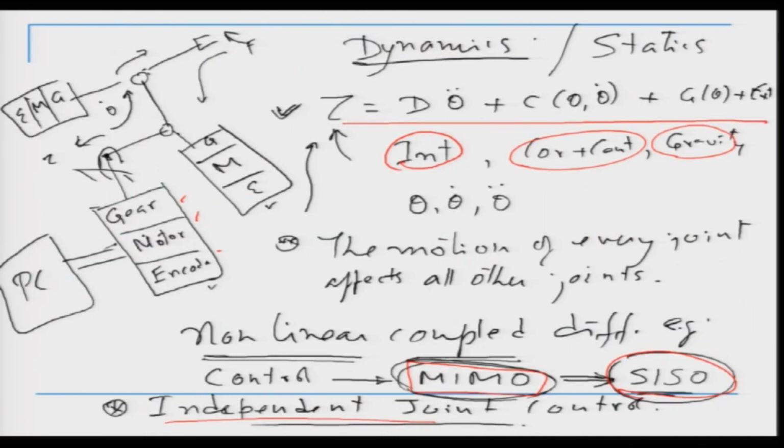So if you go back here again, this is an independent joint control, which has one block or one unit, and each of these units consists of a motor, and you would see that there is a gear in front, and then there is an encoder at the back. There is a particular reason why it is designed like this. Essentially the motor is going to get connected to the gear and it is going to go to the joint. So if there is an mg weight which is being picked up or dropped, the effect of this does not come onto the motor because there is a gear here, and so the effect of this will get divided by zeta squared, and if you have a very high gear ratio, the effect will not come. So this is something to remember.